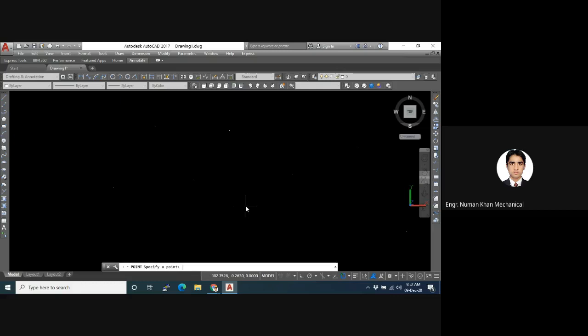Let's say it's 99. Let me change it to some specific value so that I might see. Let's say I have these points and I want to start a curve from here going like this, and I want to join these points with the help of a curve. If I want to do it with an arc, it will be very difficult for the arc to pass through all these points, because it has a specified radius, whereas here the radius is non-uniform. If you want to do it, we can do it using the spline command.